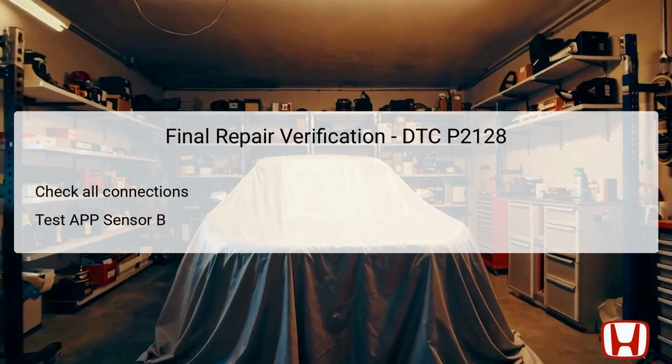Next, test the APP sensor B again with the HDS, monitoring its voltage output during operation. Confirming that the sensor now functions properly and provides the correct voltage readings is essential for resolving the DTC. Recording the new data will help verify that the issue has been addressed and that the problem will not recur.